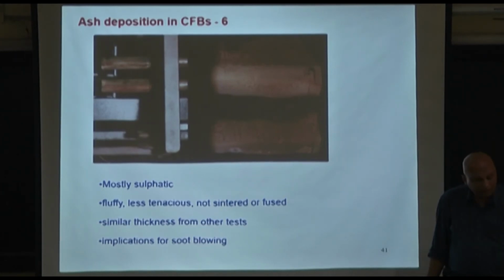So the point I am trying to make is, it's the organic sulfur which gives rise to sulfur dioxide. That's captured by the calcium oxide as calcium sulfate, becomes gypsum, a good thing to separate and then sell. But there is the inorganic sulfur that, as I said yesterday, is inorganically bonded to the coal matrix with the other minerals, calcium, magnesium, other things, iron, etc.